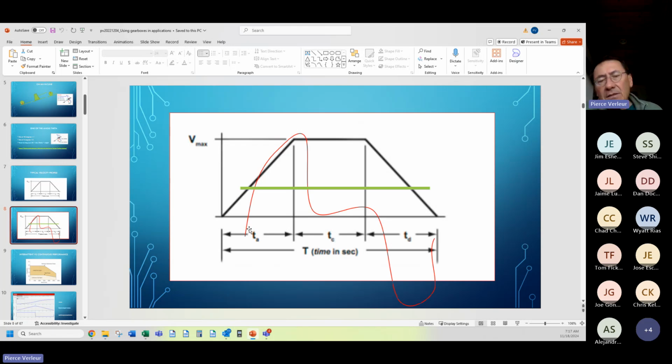A very slow accel and a long run, say 8 hours on a conveyor, the continuous duty is going to be the factor required. And the fact is that you can accel on those applications usually pretty slowly, and therefore not have any requirement to get to speed as fast as possible, thus straining the system and constraining the sizing applications of the components you're using.